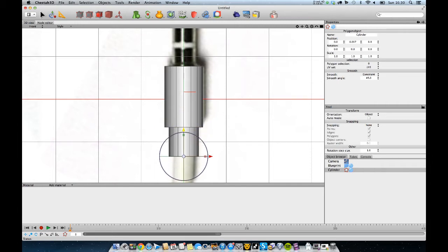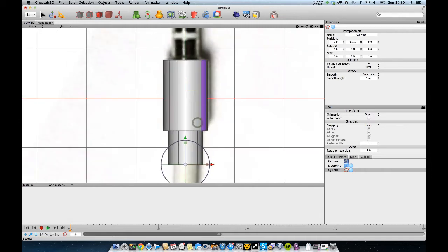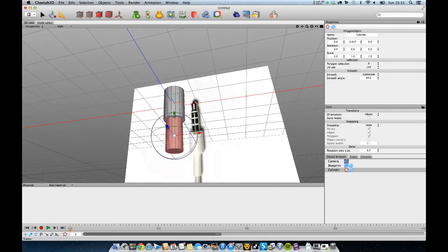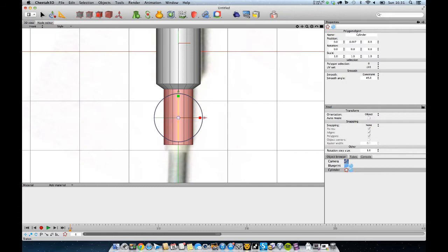Okay, so what you can see has happened there is that, because it's difficult to see in this view, I'm going to bring that down to the edge of here anyway. It's not quite the right thickness, so I'm going to press Apple Shift and X, which is going to increase my selection. Come back into polygon, into perspective view. Select the scale option and just scale in. Go back into camera 3, scaling in again. There we go, and I'm going to just drag this up.